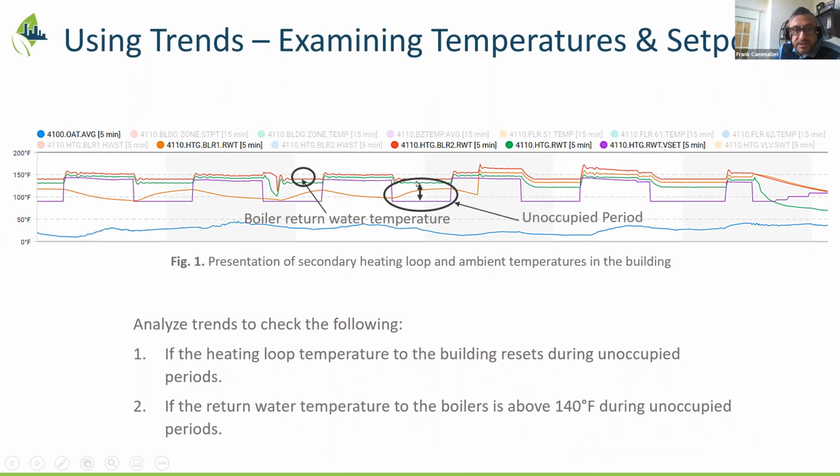Right, so you're seeing that this stayed up at 130. Well, if all the individual convectors or their valves are opening up because you're trying to cool off the building, 130 degrees still gives off quite a bit of heat, right? So we were trying to figure out why that isn't happening, and that could be a big contributor to loss of savings, for instance.